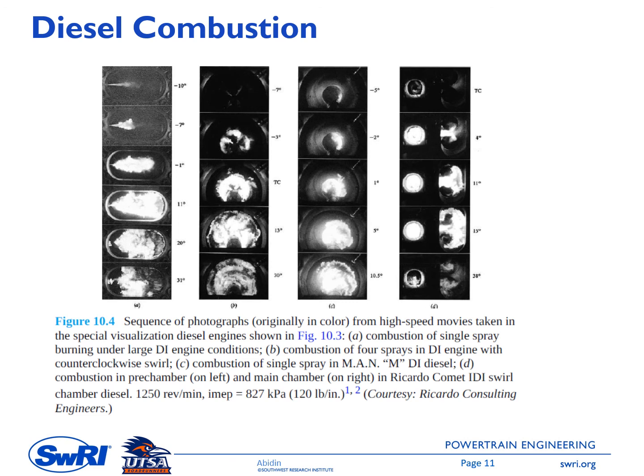So there is no swirl here. If you see the spray direction, it just moves simply from left to the right. There is no velocity upward or downward. So here the condition in which the spray is injected is a quiescent condition.